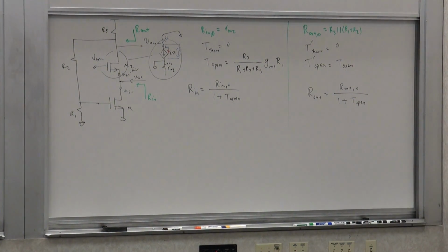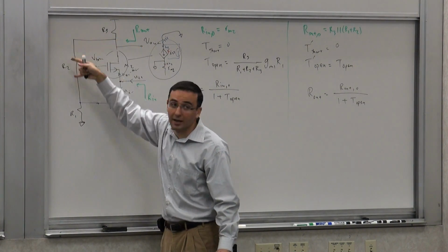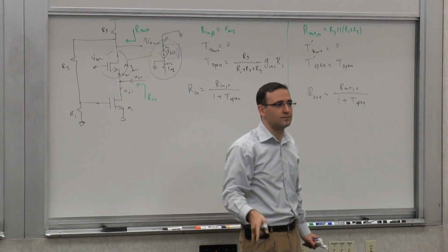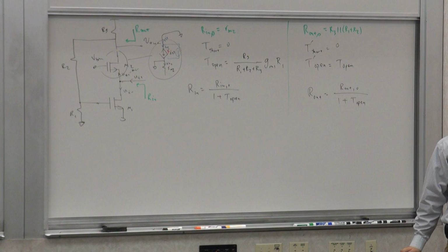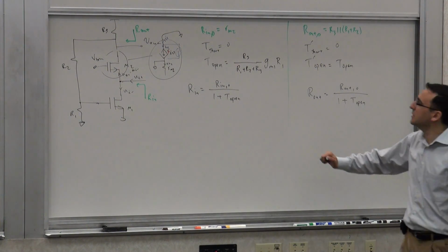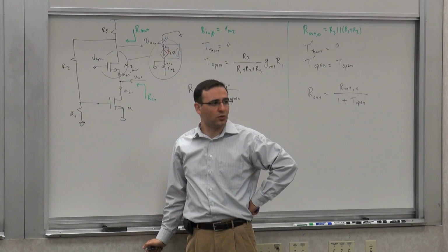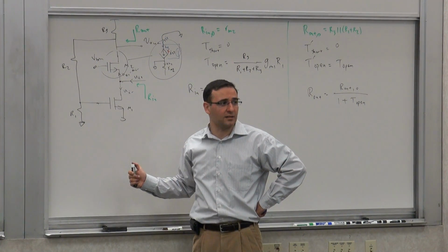So you see that output is also a pure shunt. So basically it means that you are doing a parallel voltage metering. So you're measuring the voltage here in parallel perfectly. So, again, not spending so much time on names, but would this be a shunt-shunt? It's a shunt-shunt. Meaning that you're measuring the voltage at the output and you're returning the current to the voltage. Current feedback for shunt-shunt.